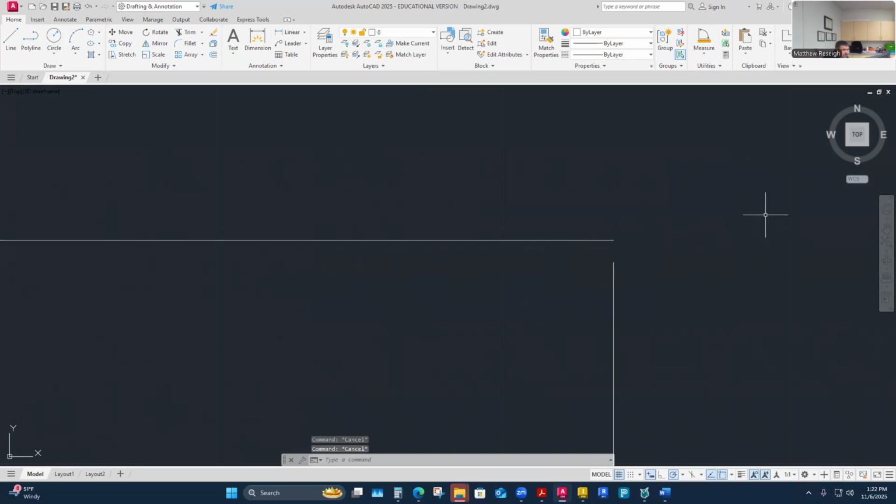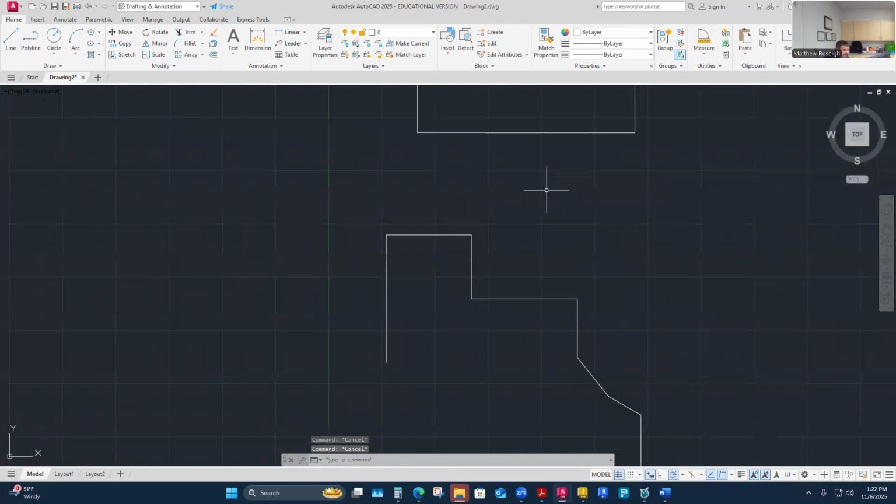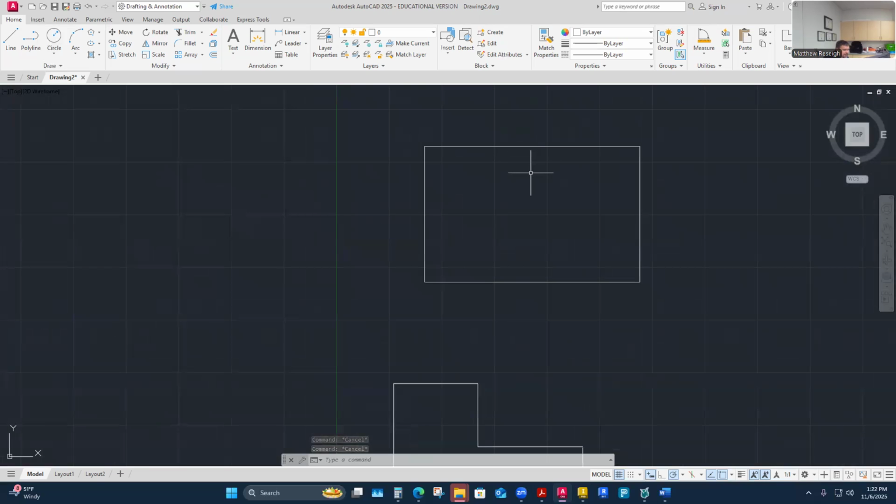So usually you'll see me draw with lines when we go to draw next time, but sometimes I turn my lines and join them into single selected geometry. That way I know that everything is connected. I know that when the machine goes to cut this, it's going to be able to cut these lines, and it's not going to have broken stuff that's not intersecting itself, or extra lines drawn over itself.